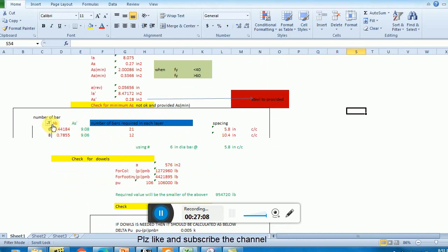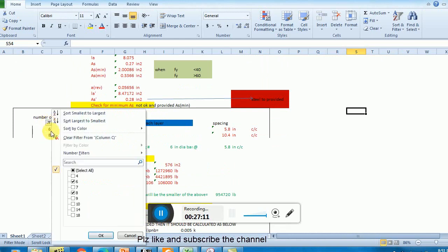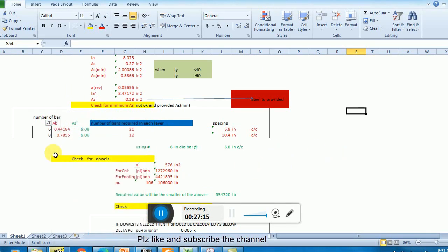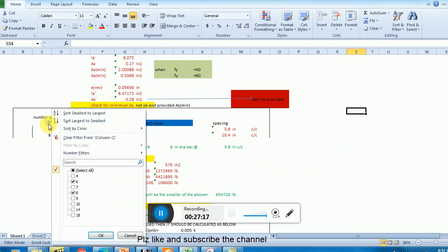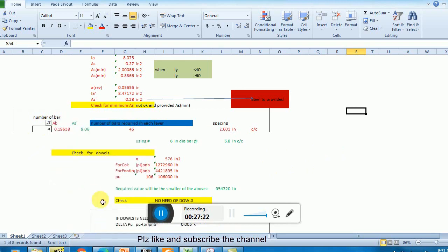So that's why we have to use AS provided, AS minimum. And here you see how to use this table. Now as we are using number 4 bar, I check number 4 and uncheck number 6 and number 8 bar. So this is the bar area of number 4, and now we have to change this. As prime is basically the total area provided to the column.